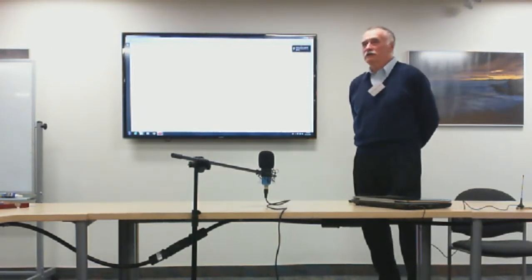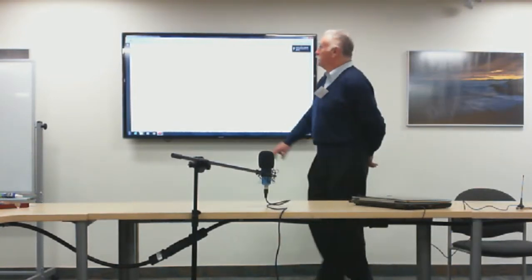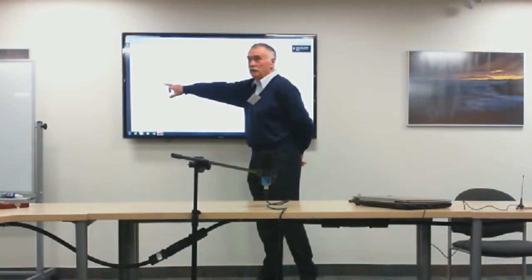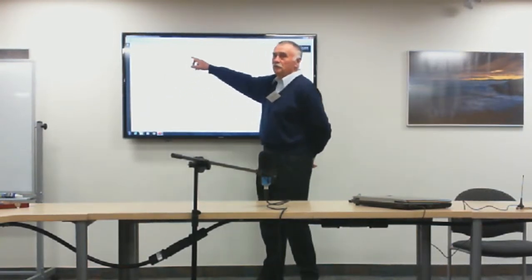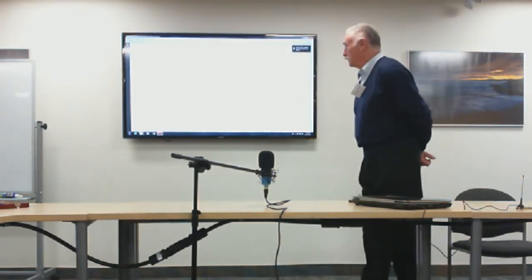In my opinion, it would be simpler if they would say that since in all likeliness your amplifiers have an efficiency no better than 76%, that's what we allow you to use. So the 190 watts carrier is plainly 76% of the 250 watts allowance of power drawn from the batteries.